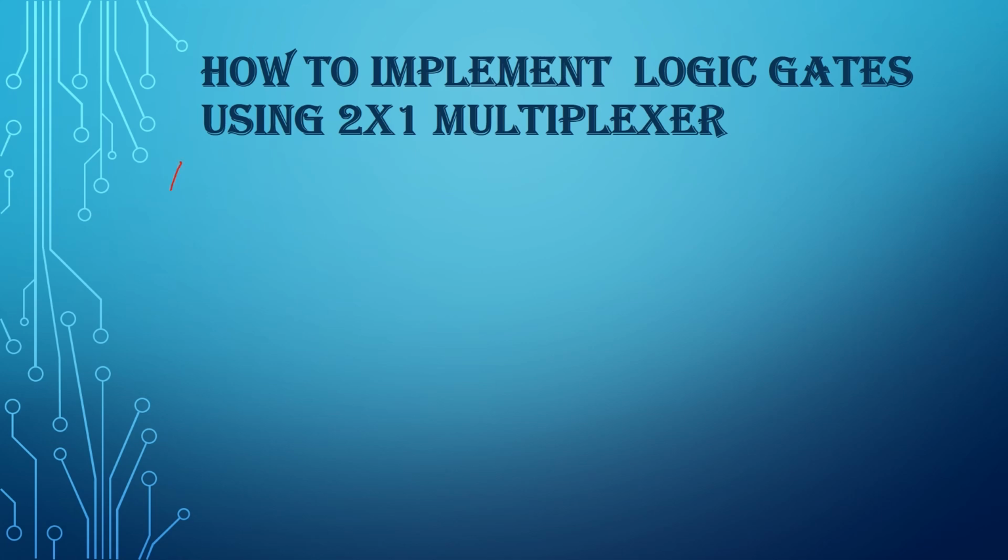So, as we know, AND gate has two or more inputs and one single output. Here I am considering A and B as the inputs and Y as the output. The combinations are 00, 01, 10, 11. If both inputs are high, the output is high, and the remaining are 0. And this is the truth table of AND gate. From this truth table, we can write the logical expression as Y is equal to AB, and this is the symbol of AND gate. The inputs are A and B, output is Y.